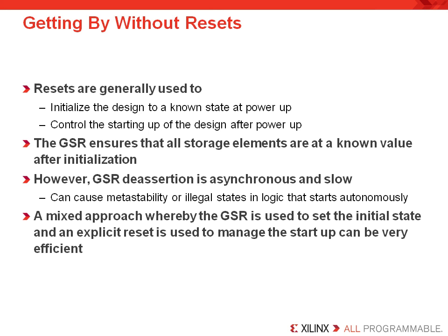Recall, configuration takes a few milliseconds. So there's plenty of time there as part of configuration at the FPGA to actually reset everything in the design to that known state. But if you actively drive a signal onto the GSR, keep in mind, again, the routing is slow, and that could cause a metastable situation or create an illegal state in your logic that starts autonomously.